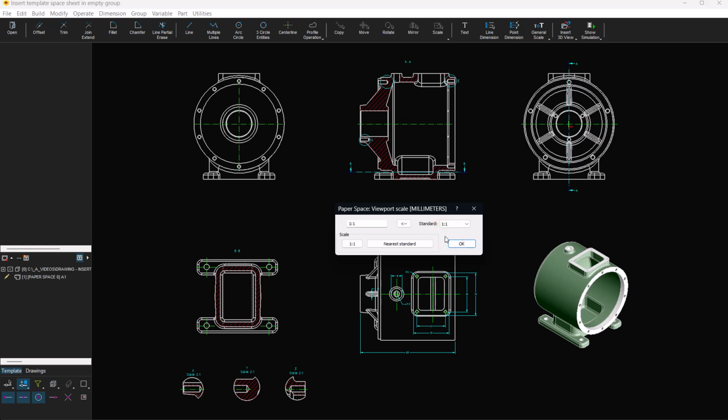Note that the details are already in 2:1 scale. However, we could have created in the drawing environment the details with a scale of 1. Then in paperspace, creating the viewport's details with a scale of 2.